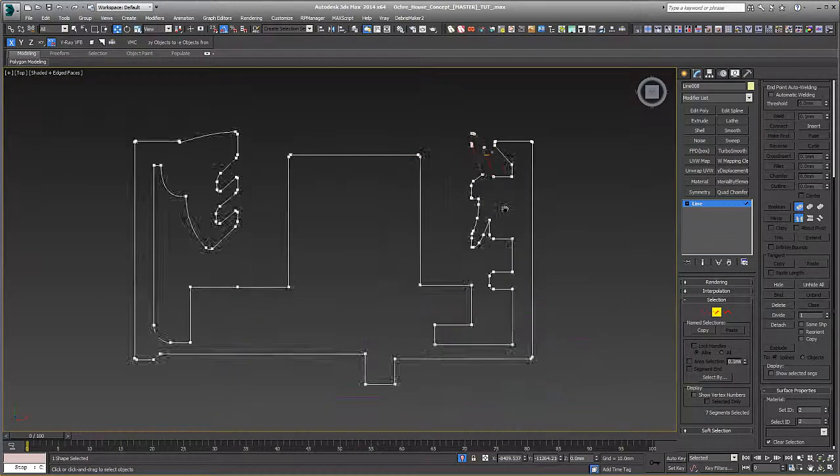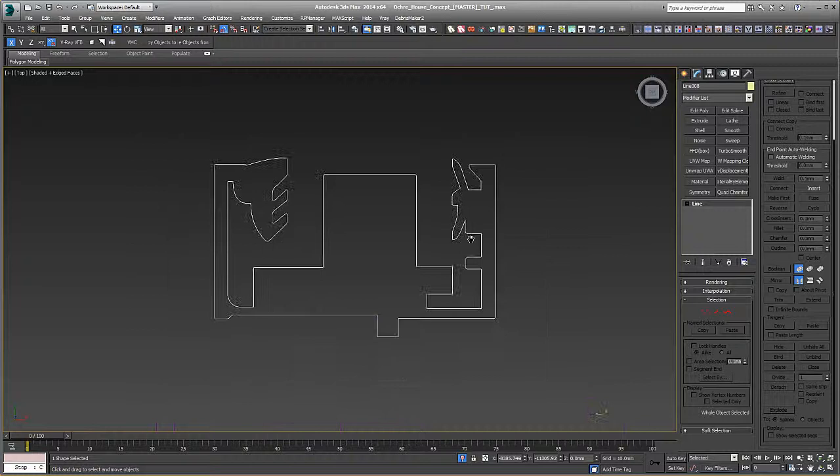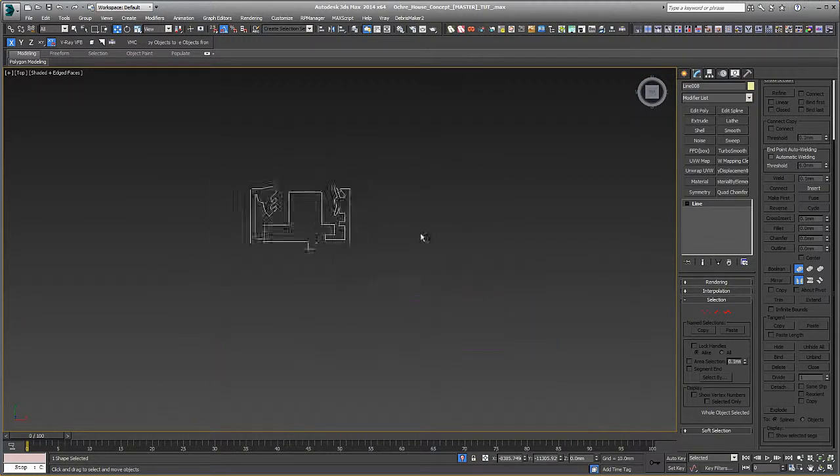This enables me to give a different ID to the areas I want to be rubber seals, and then I can just use a multi-sub object, and I don't have to select polygons and add IDs myself. It will automatically take these in the sweep with a tick box. But we'll show you an example of that once we've modeled the window.